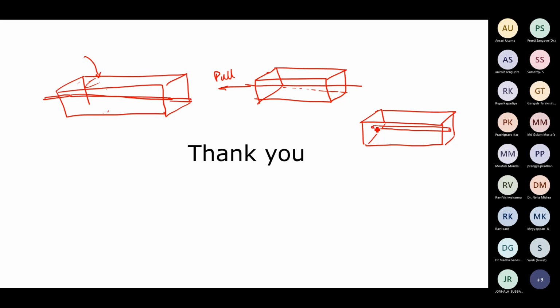And now simply you can put the stainless steel connectors like this, and you can connect this to a tube. Therefore you have a very simple microchannel. So the thinner needle you use, the thinner will be the microchannel. So there are various ways of getting the job done. One need not be always restricted by photolithography.